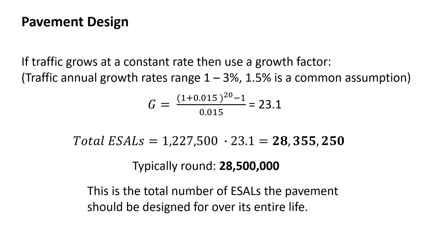So this ESAL number that we were calculating is how many ESALs that pavement is designed to handle over its entire life. I think that throws people off, and they think we're designing that ESAL number per year or something. Nope, it's like money in the bank. Every time a truck drives over that pavement, it subtracts dollars out of your bank account. You start at 28.5 million.